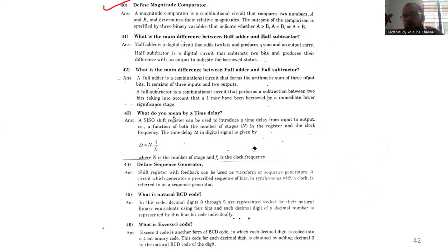First of all, you have to draw the truth table. Later, you have to solve it by using the K-map. Then simplify it; reduce it to the maximum. Later, you have to draw the logic diagram. Based on that, you can rig up: identify the gate ICs, and put them on the breadboard, whatever it may be. We use the breadboard.